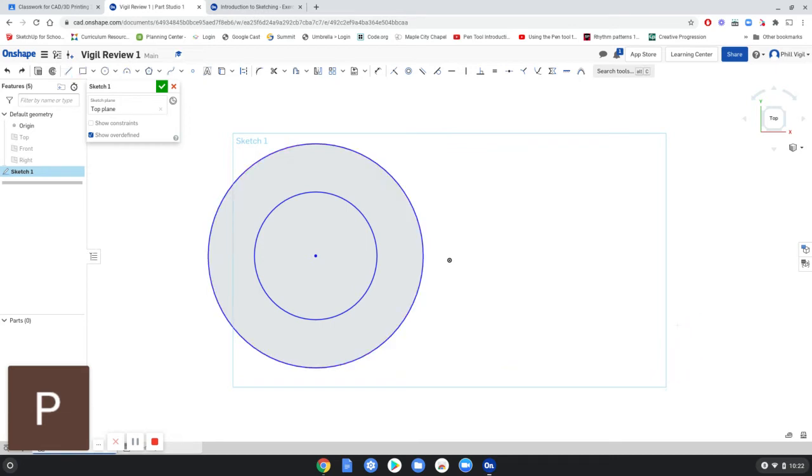Let's go ahead. You can go back a step if you want to by using Control Z. So as I near the perfectly horizontal, I get a little symbol that's a dash indicating that it is perfectly horizontal to my drawing plane. So I'm going to use that for this first line. Then I'm going to go up perfectly vertical, and I get that screen tip there. That's a vertical line. Then we go back horizontal, then up vertical.